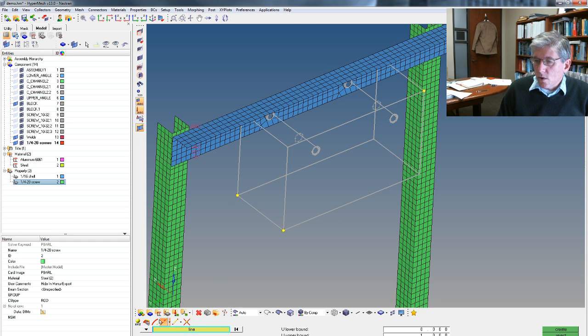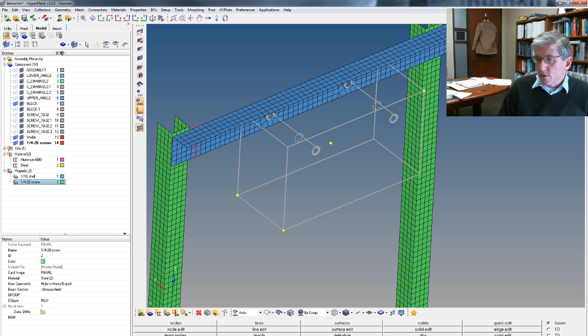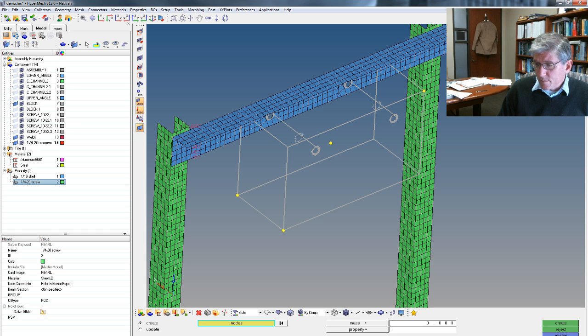And then basically, I will put a node between these 2 points, between this point. Okay, wait, node list. Between this node and this node. All right, and that puts a node right about in the middle. All right, so now let's put the concentrated mass element here, which is a CONM2. Again, so that's going to be under 1D masses, and there it is, a CONM2.